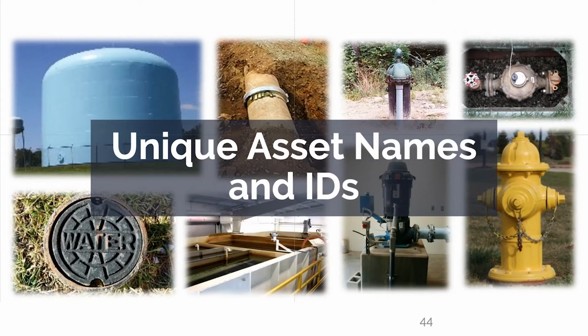We do a lot of pipe break analysis for utilities, helping them try to decide what should be replaced and in what order. And we quite often see pipes that have been replaced within the last 5 years that have break data associated with them that goes back decades, because the new pipe basically had the same asset ID number as the old one. So then we have to go through and sort of segregate all that information. So if you give your replacement assets a new asset ID, you're going to be in much better shape, because you're going to be able to associate meaningful information with your new assets and not associate old outdated information with them.